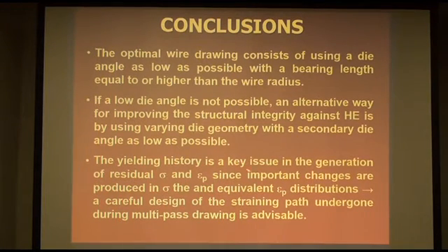The yielding history is a key issue in the generation of residual hydrostatic stress and plastic strain, since important changes are produced in the hydrostatic stress and equivalent plastic strain distribution. As a consequence, a careful design of the straining path, the straining history undergone during multi-pass drawing, is advisable.